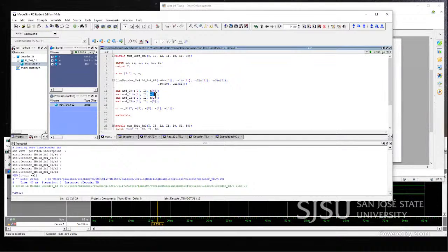Individually, it connects to each of these outputs from the decoder with the incoming input line. And that becomes output from each individual, which, for my code writing easiness, I just use as an array of wires. It's just a 4-bit array of wires. It becomes an individual bit.